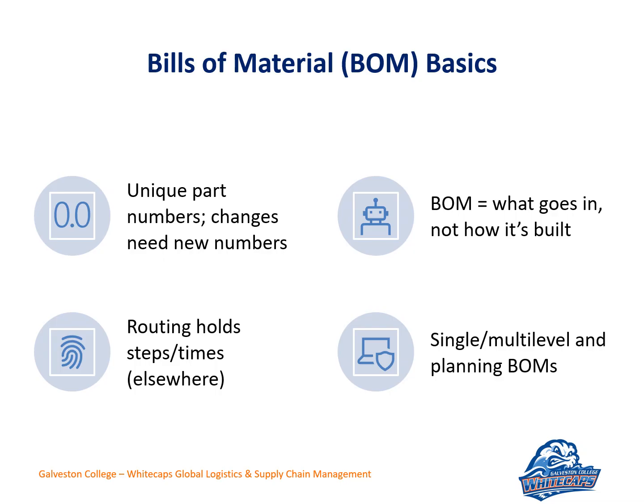Eventually, we automated that, so when we scanned the production order, it would verify that it's the most current bill of materials and the most current rev, and they could feel confident that they just needed to check for these parts. Those are some interesting tie-ins when you think about building these products. And anytime you do a change, it's either a rev change or a part number change.